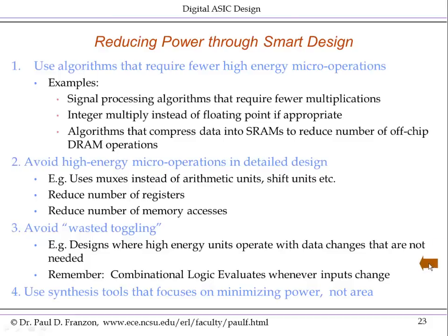A good example here is if you have combinational logic units, large ones such as say a multiplier. Remember, if the inputs change, the module reevaluates whether you actually use that output or not. Finally, there are synthesis tools and options within the synthesis tools that focus on minimizing power rather than minimizing area. And these can make useful differences in the end power consumption.